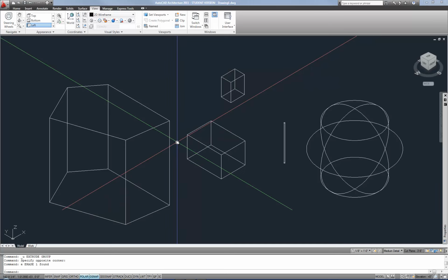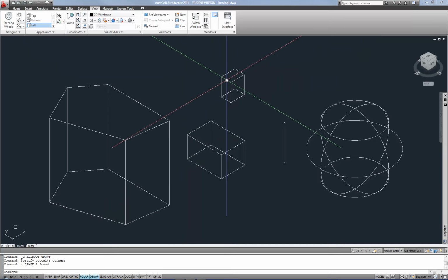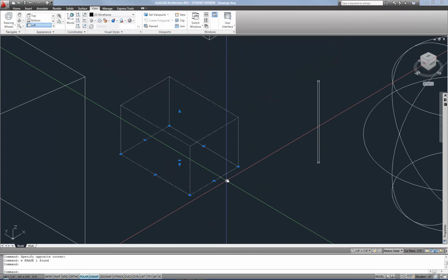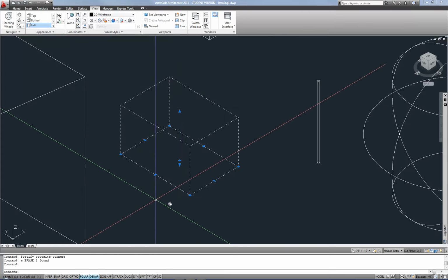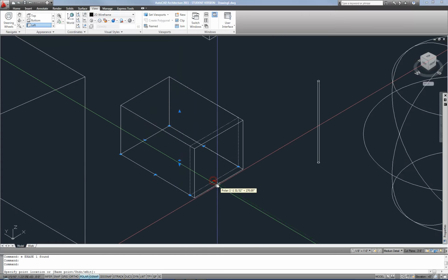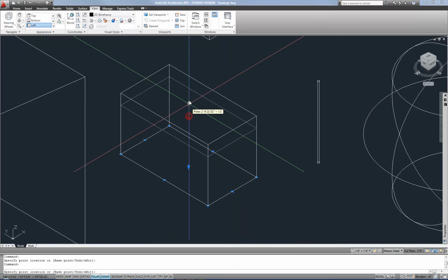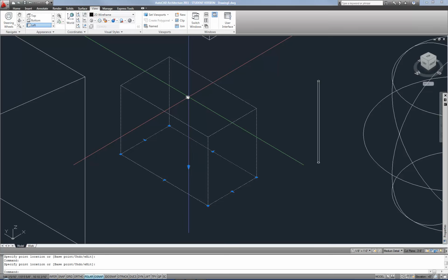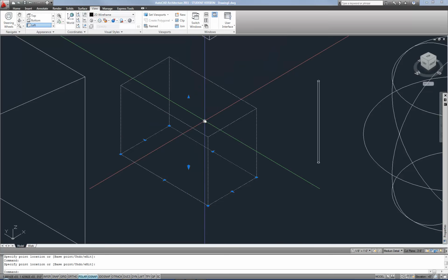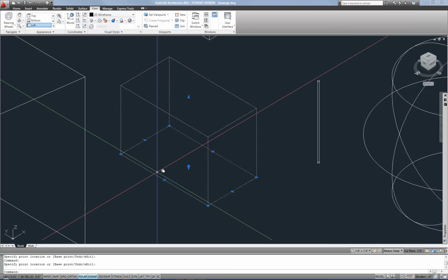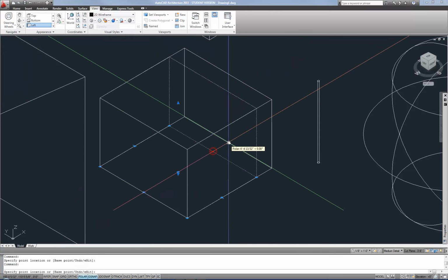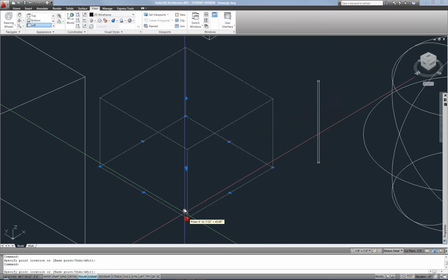Now all these shapes are pretty easy to edit after the fact if you use the grips that are available to you, especially the 3D box forms and other simple forms. They have grips at each corner and at each side, so I can extend this out in that direction and up in that direction. And so the grips do allow you to work in directions other than the XY plane. I mostly say that the standard move and copy commands, things like that, are what are very constricted by that UCS icon. So the grips make it very easy to enlarge or shrink down your shape.